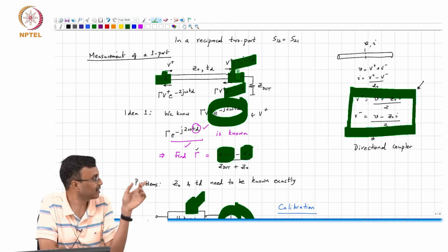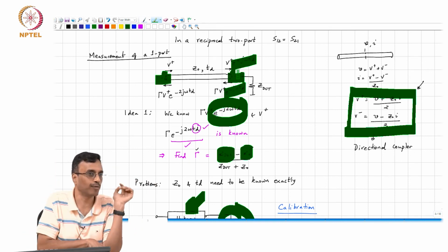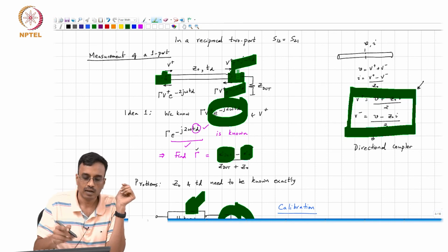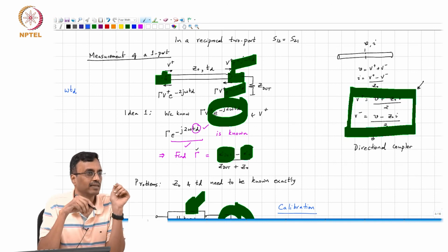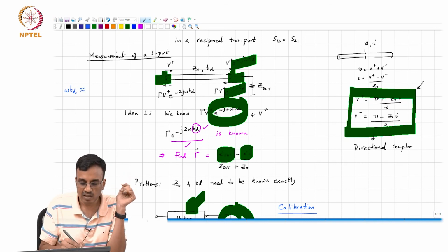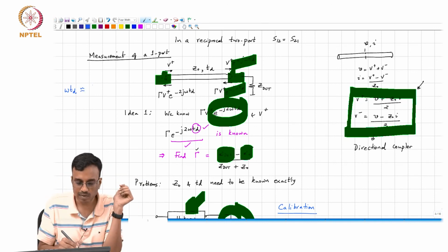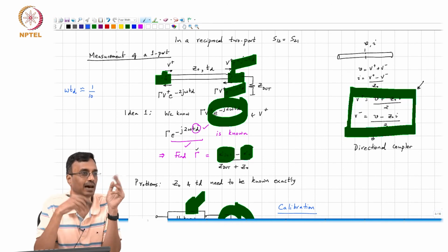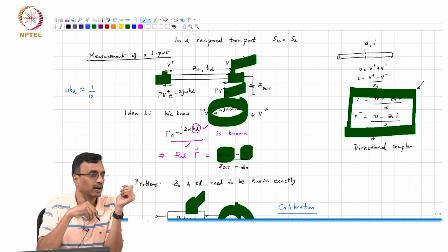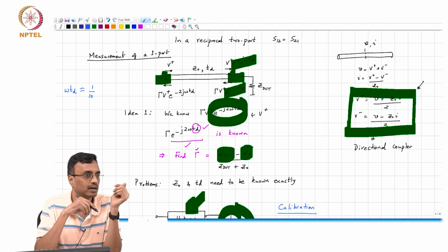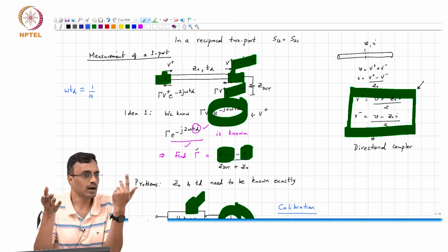So at high frequencies, and what is the meaning of high frequency therefore? This omega times Td is a significant fraction of, say, maybe 1/10, arbitrarily. I am just saying 0.1 is bad enough. And what is Td in terms of length and omega?